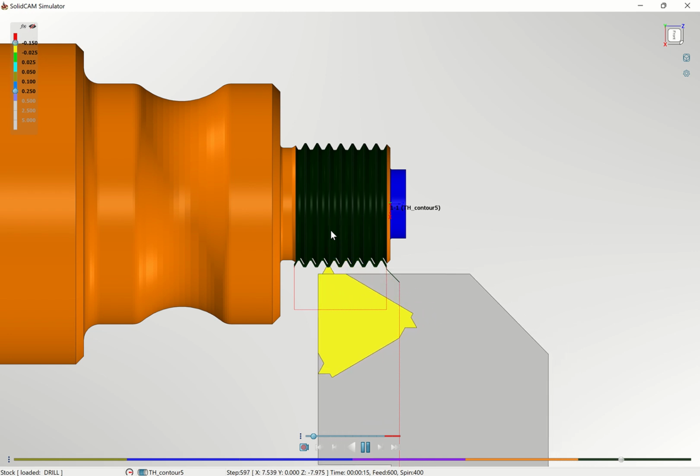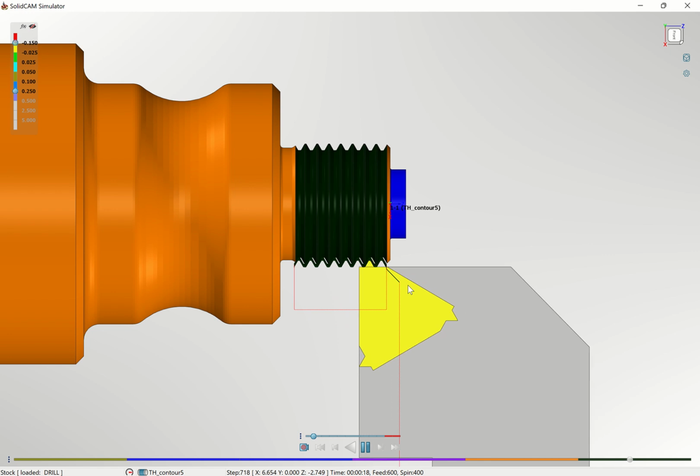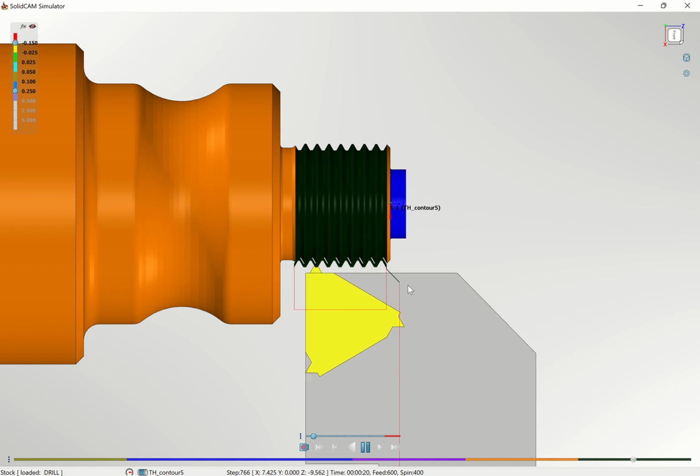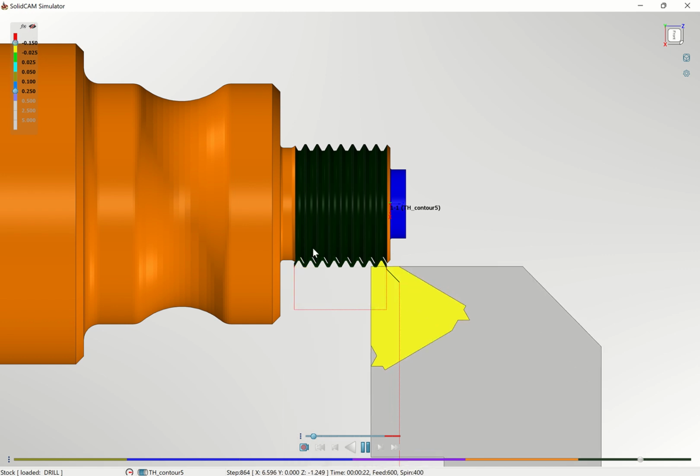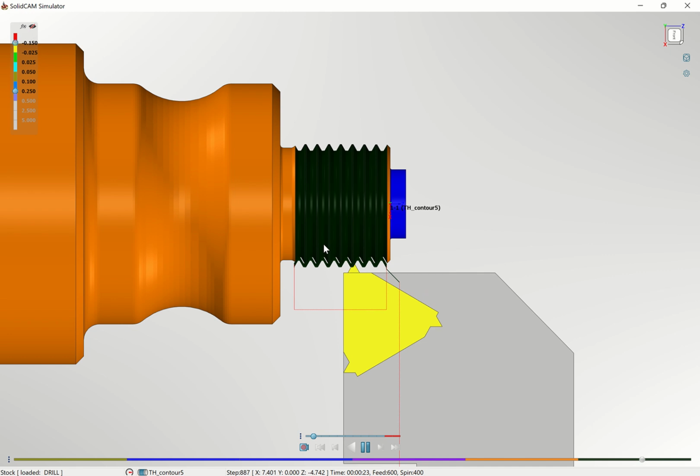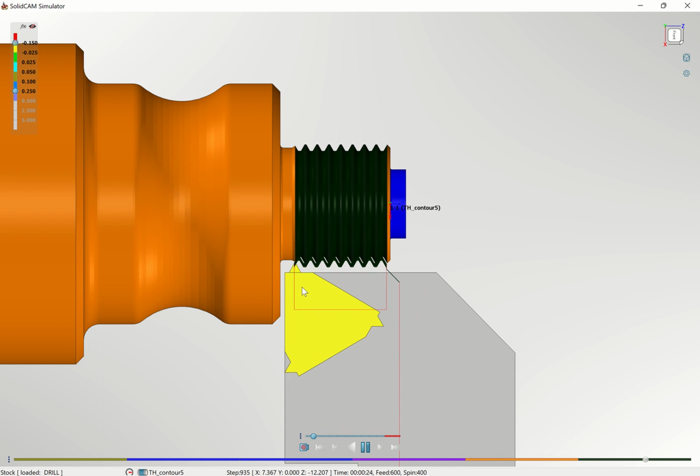Designing is very critical, also ensuring that when you are designing for manufacturing, you are not just designing for the sake of designing. If you are designing for casting, design for casting. If you are designing for 3D printing, ensure you factor in the tolerance for 3D printing. If you are designing for CNC machining, ensure that you design it for machining. If it's laser, plasma, or jet, or all those kinds of operations, ensure you balance the tolerance for each operation so that you don't incur a lot of excess material or inequalities in the material uniformity when the tool has done its operations.